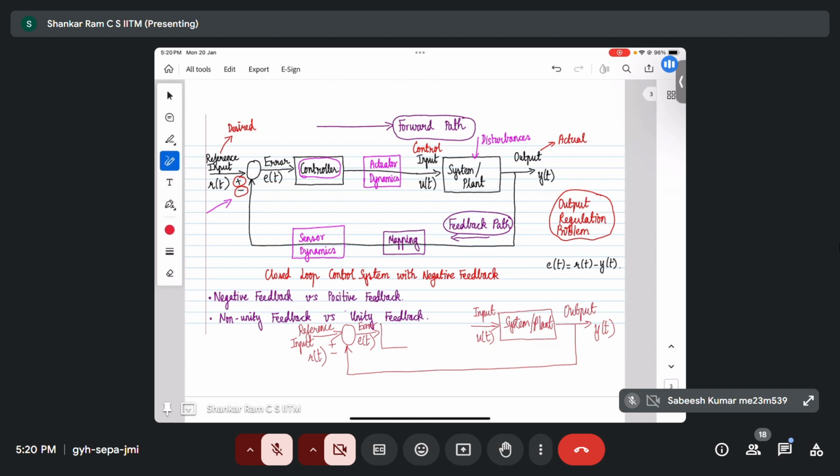And then I take this error E, which in this case, let's say it's 10 kilometers per hour. And then I pass it through a controller, which will then calculate what should be the input that I should give to my motor. Okay. Then this input U of t is what is called the control input. So you can observe how I drew the diagram, right?